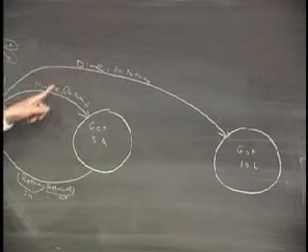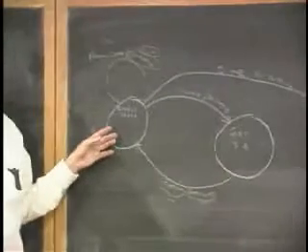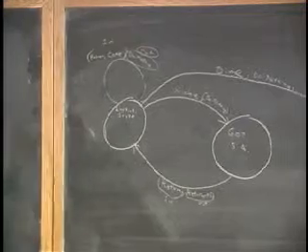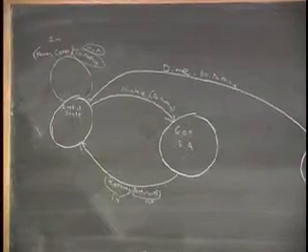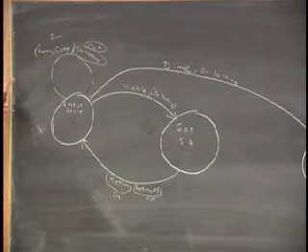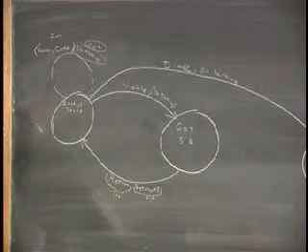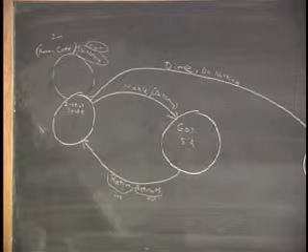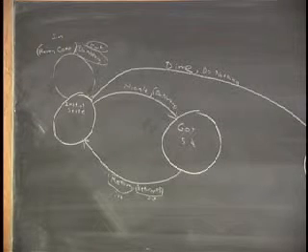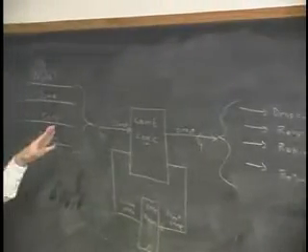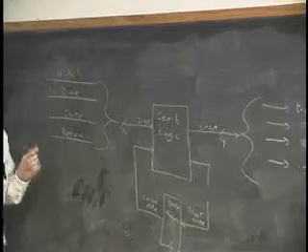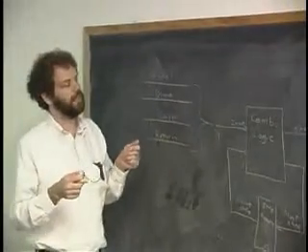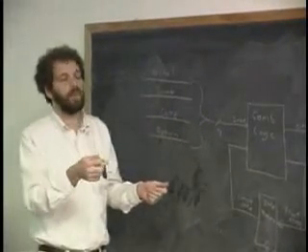Now, if I were really being careful designing this Coke machine, I would actually have to say, what if he presses return and puts in a dime at the same time? Because that's actually a different combination of inputs. Remember, there's 4 bits here, so it's not that there's 4 combinations. There are, in fact, 16 different things. But it actually used to be the case that if you pressed give me a Coke and give me my money back at the same time, and you got the timing just right, the machine would give you both.